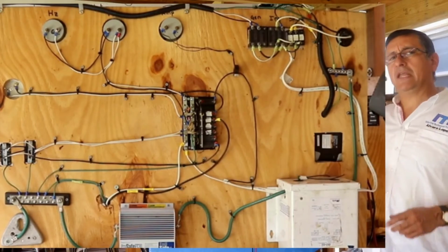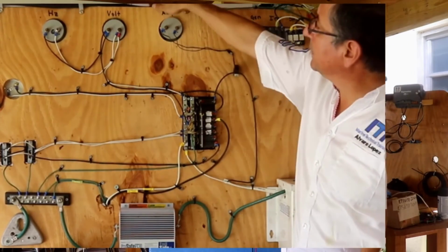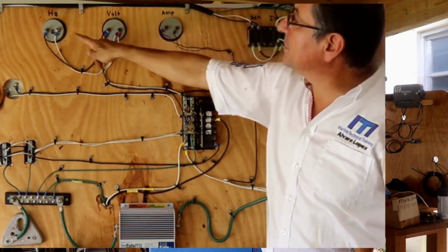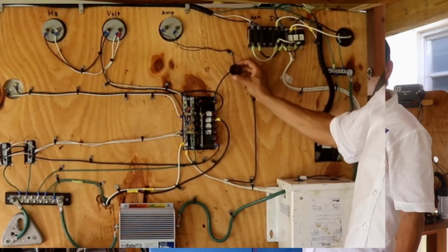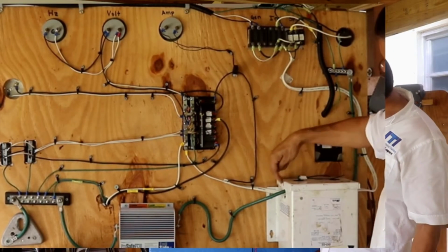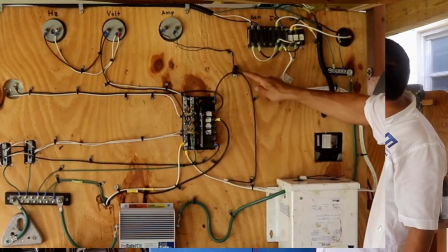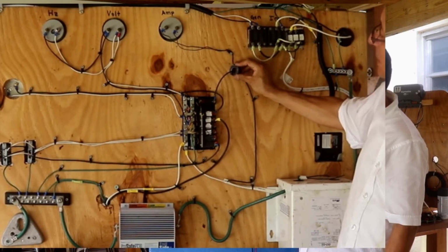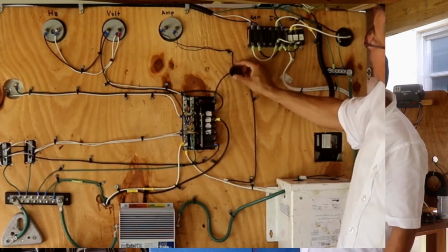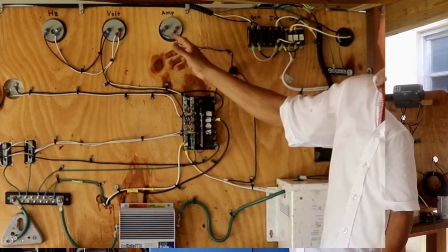Now we are going to connect the voltmeter and the ammeter. This is the ammeter, this is the voltmeter, and this is the frequency. The ammeter has the donut, and this is the hotline. You remember the hotline coming from the output of the transformer enters here, passes through, and enters the main breaker. And the donut is here. The cables in the output of the donut enter each terminal of the ammeter.